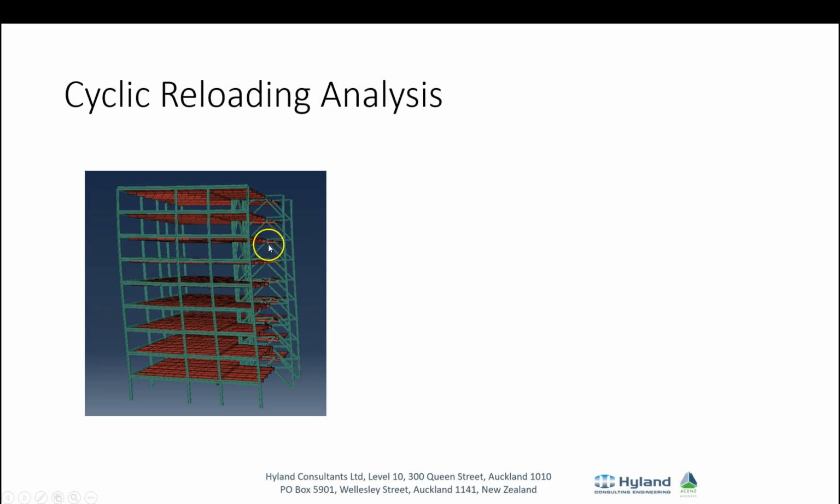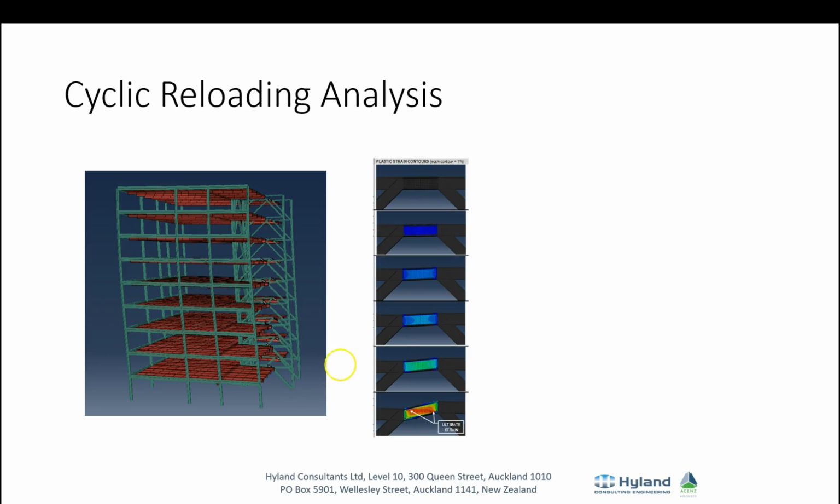We knew at level 6 of the building what the peak rotations were, and we'd also had a look at what the cracking in the slab was, and this indicated a certain amount of deformation. We then tried to replicate that with rotations of these links, and just to see how the strain built up in them.